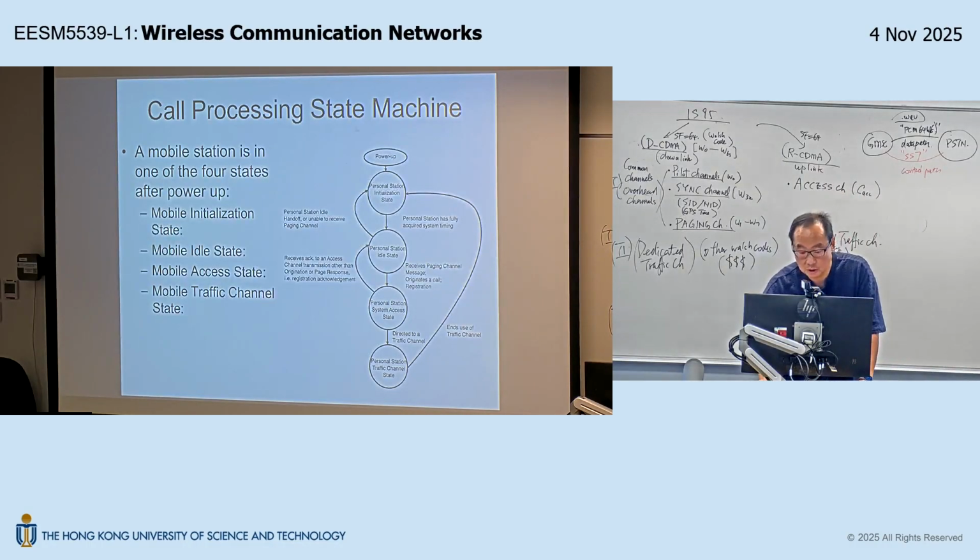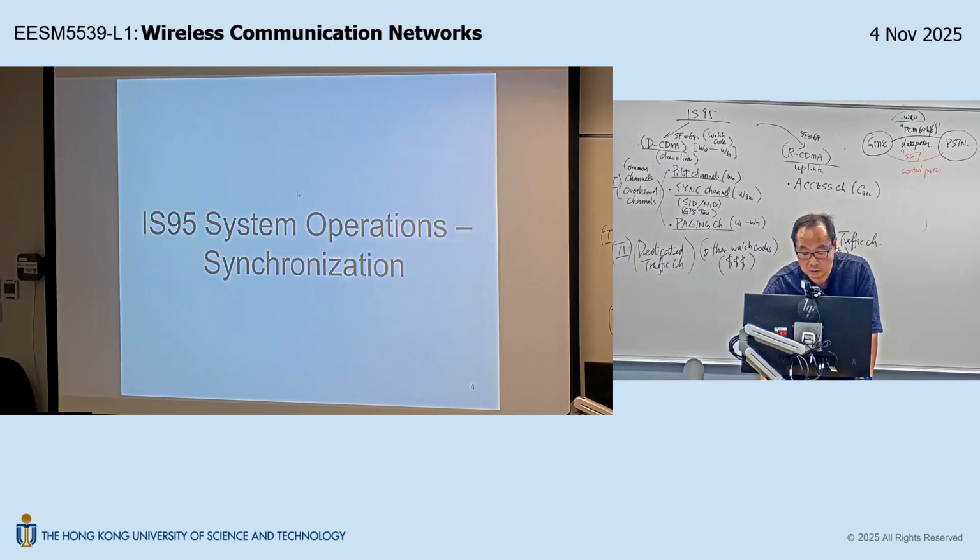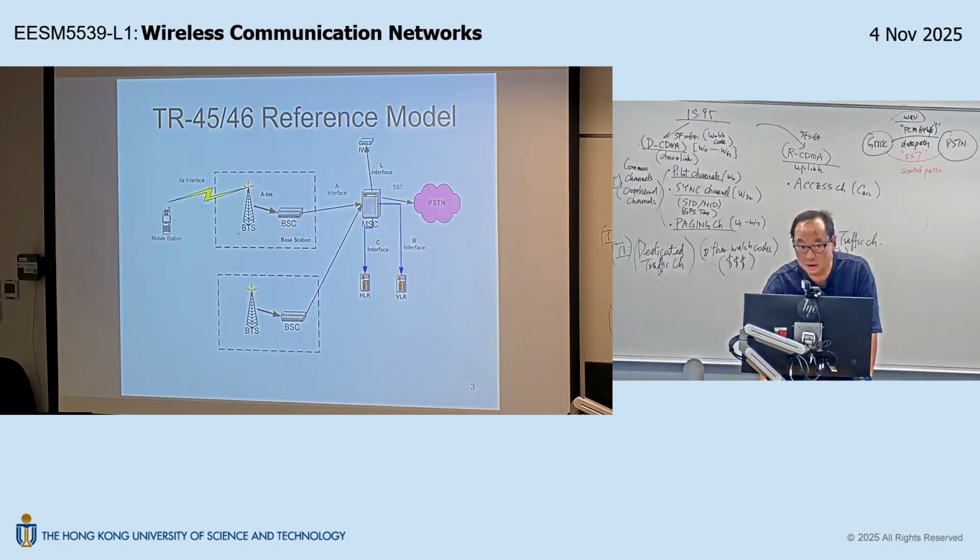Now, for instance, the CDMA system in IS-95, if you look at this architecture, is a synchronous system. Synchronous system means all the entities in the network run on the same clock. So the base station and the base station controller have the same notion of t equal to 0. They run on the same clock. The mobile switching center also has the same notion of t equal to 0 compared to all the other entities. Okay? So how do they do that? Now, these are the fixed line entities, so they are connected by cables or optical fibers. So they can have their own synchronization system.